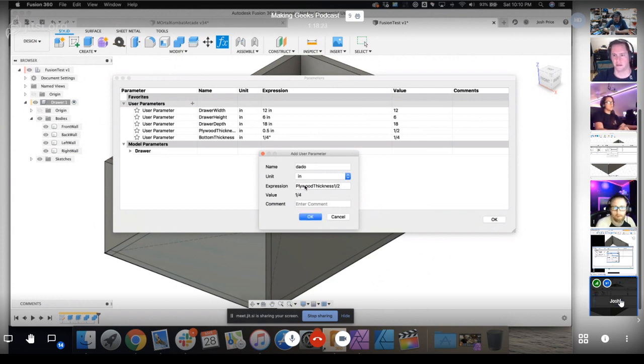Do I get that? Is there a reason you did that? Can you explain that? Yeah. So when you're woodworking, does everybody know what a dado is? Yes. So a dado, we're going to cut a channel into the side wall. We don't want to cut too deep into that wall so that it weakens the structural integrity of the wall, but we also don't want to cut too short, so if we apply a downward pressure to the bottom, it could potentially pop out. Okay, I got it.